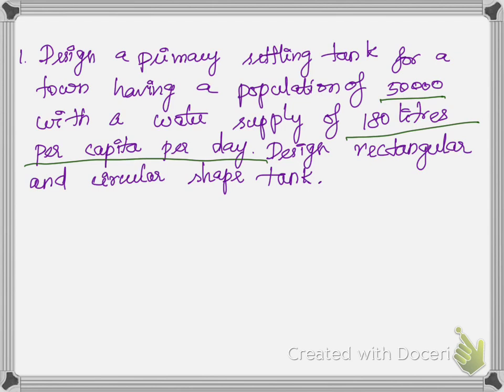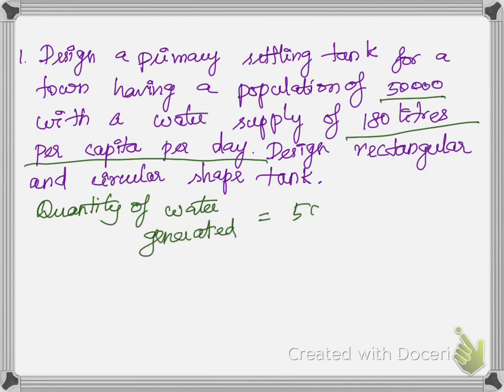First, we have to calculate the quantity of water generated, which is population into per capita demand, 180 liters.